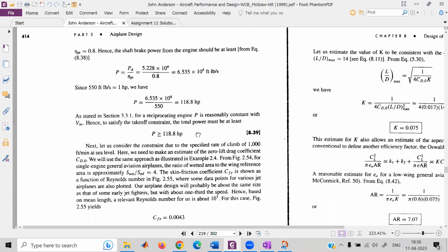So going ahead, we need zero lift drag coefficient for all those calculations. We'll see the actual expressions later on, but at this juncture, we need to estimate that. So in one of our sessions, I discussed about weighted aspect ratio. Anyone remembers that? Yes, sir, weighted aspect ratio. Yes. How do we define it? Sir, it is the area which is in the airstream outside, which is interacting with the free airstream. We can say that. Yeah.